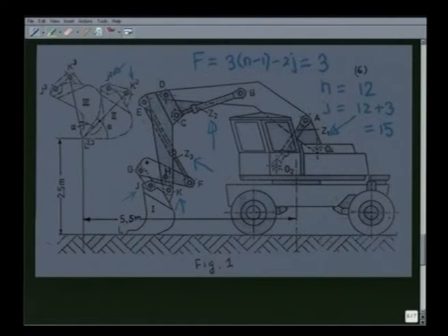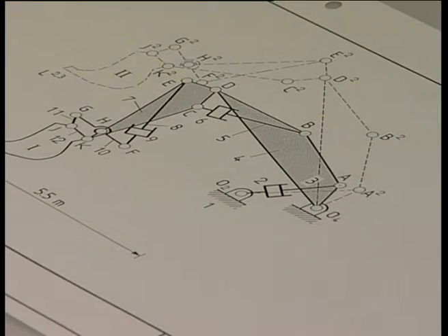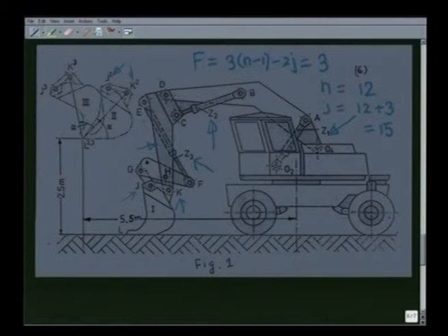Second thing to note is that there is a very high order link which is connecting at C, D, E, H and K. That means, this particular link has 5 revolute pairs in it, and it is a link of 5th order. So, we will show how we can use the tracing paper very conveniently to locate the revolute pairs in this kind of higher order link. Let me now solve this problem: when j and k move to j2 and k2 respectively, how can you locate all the other moving revolute pairs, that is at B, C, D, F, H and G and A.